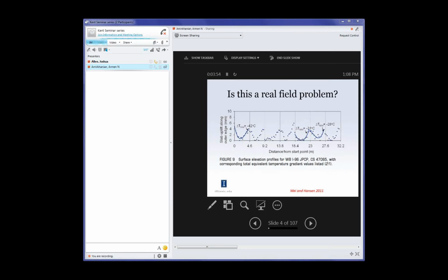So with curling in general, it is an actual problem in the field. These are field measurements taken on multiple slabs. The vertical lines indicate each slab boundary. And you can see this dominant U shape appearing in each slab as you take essentially dipstick measurements across the slab. And the deflection from the center of the slab to the edge of the slab in some cases goes up to 6 millimeters, which is huge because you only need about 2 millimeters of upward deflection to crack a slab under load. So 6 millimeters is not good. And this is just a jointed plain concrete pavement, so it does not have dowel bars. The dowel bars would definitely reduce this amount of curling, but curling has been seen even in doweled pavements because both slabs will actually bend up.